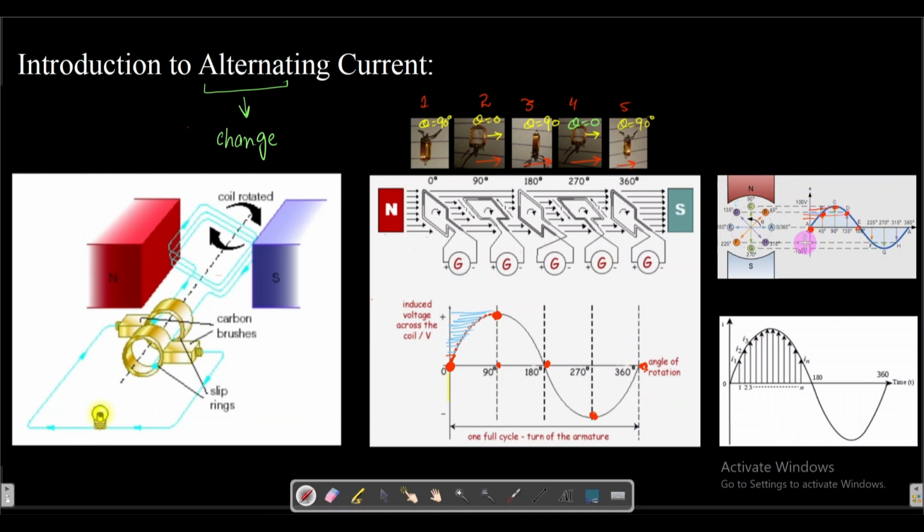Okay, and on the vertical axis, the y axis, we have this EMF value. Again, for 225 degrees it gives us the EMF value but with the negative sign, which is given by the Fleming right hand rule. And here at 270 it becomes again maximum at the negative side, and in this way this alternating current is changing its magnitude with time.